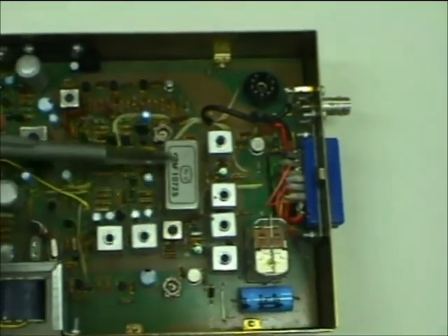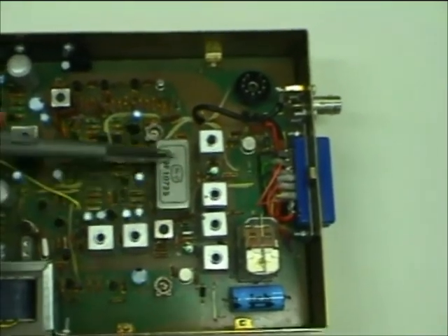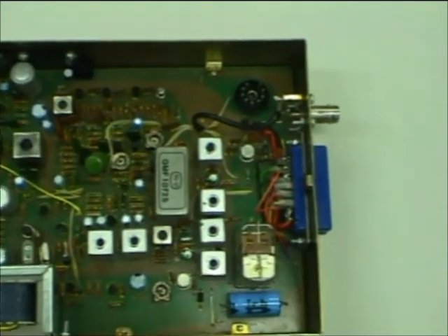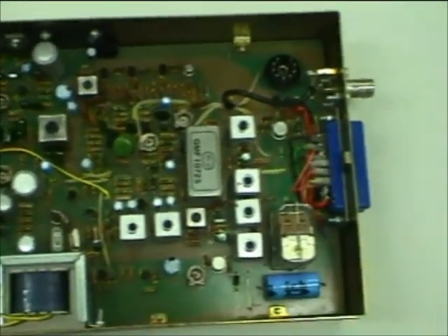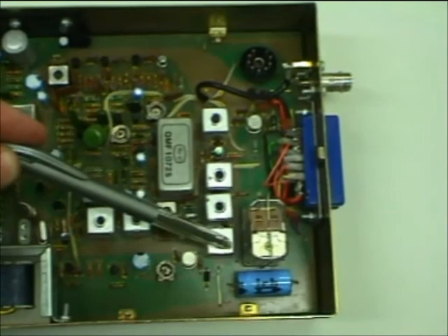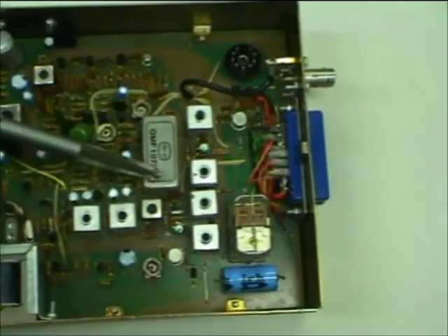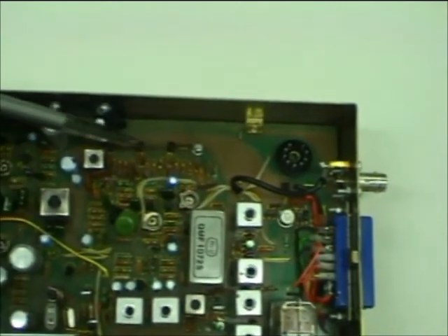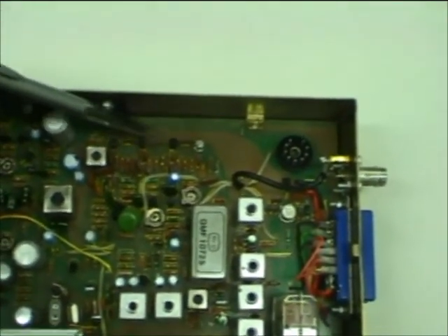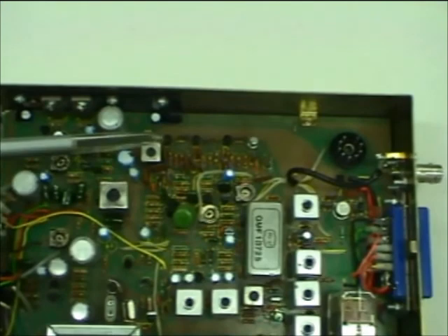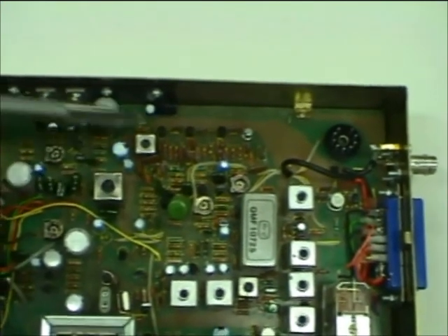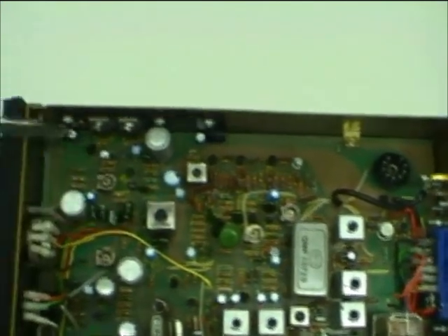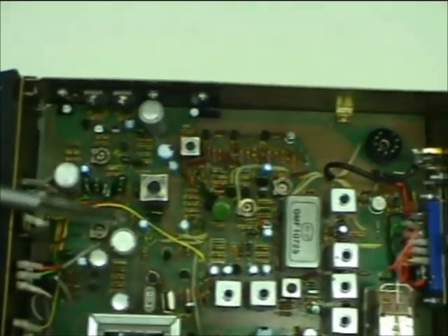And then into the intermediate frequency filter. That's the IF filter running at about 10.7 megahertz, setting the selectivity of the receiver. So this arrangement's giving the image rejection. That's the mixing. This is giving you the selectivity, and then it comes out through that field effect transistor. These 3 transistors are the IF amplifier, and then the AM detector is around here. It's an AM receiver, and here's the sound amplifier.